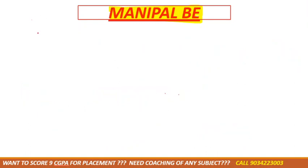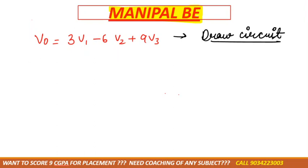Now the last category of the op-amp, that is V0 equal to 3V1 minus 6V2 plus 9V3. They'll give you a question like this, and they'll say you need to draw the op-amp circuit. Now see, in this case two signs are the same, this one and this one.